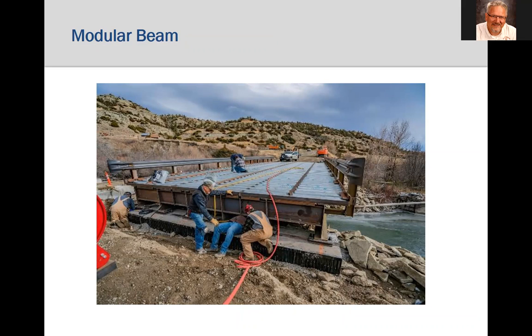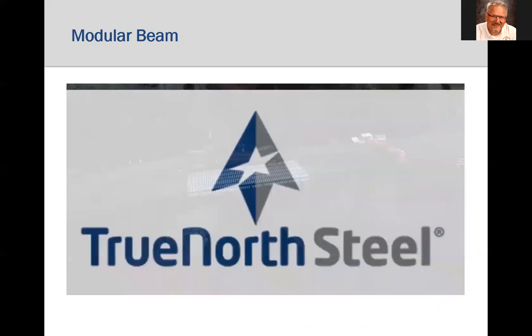True North's prefabricated steel box called the Supersill abutment and ABC abutment were shipped to the site and installed prior to delivery of the bridge modules. Starting in the morning, the local county crew and a crane set the 3 8-foot by 65-foot bridge modules by lunchtime that day. This video shows the construction of the Sweetgrass Bridge.